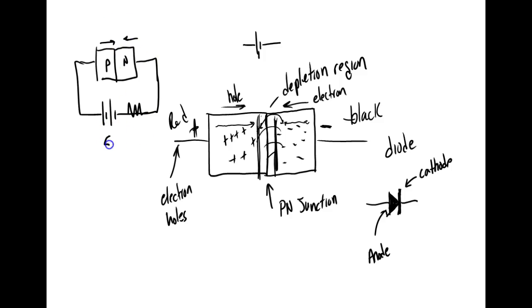This guy, if this is 5 volts, if I measure across this diode, we would get approximately what? 7/10, and 7/10 is an approximation. That's not a precise thing. And this resistor right here would measure 4.3 volts because it's a series circuit. But if I increase this to 10 volts, then the diode is going to drop about 7/10, and then my resistor would end up dropping about 9.3. Are we okay? Pretty neat.